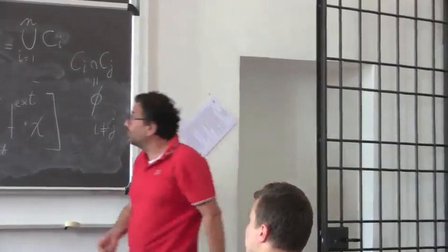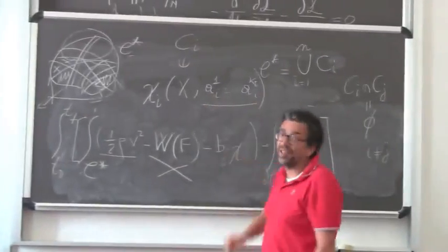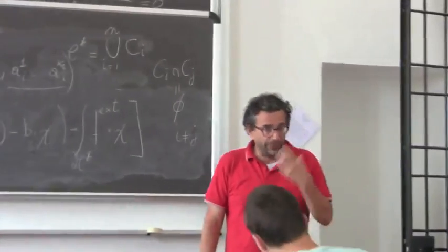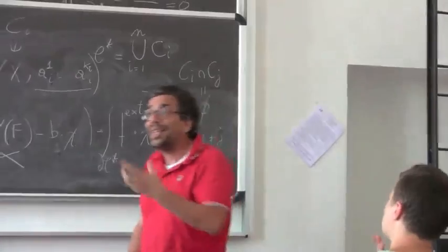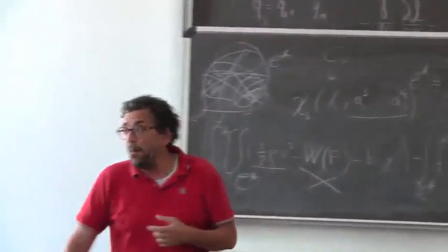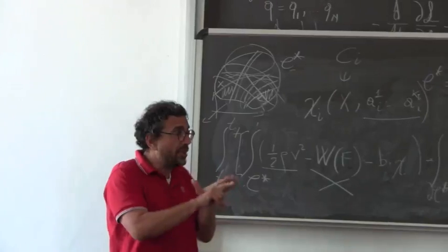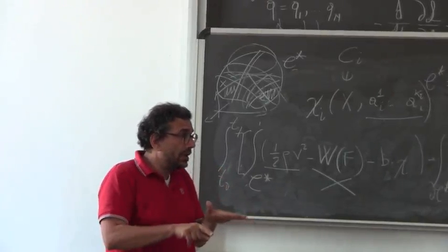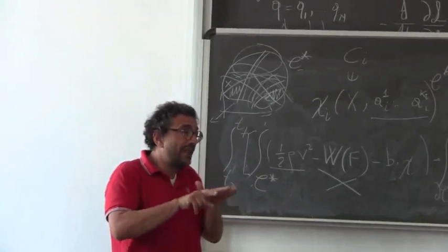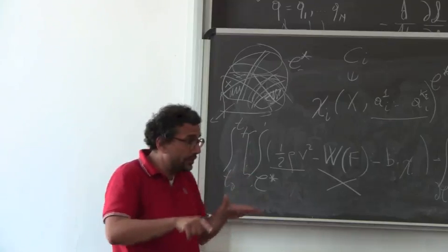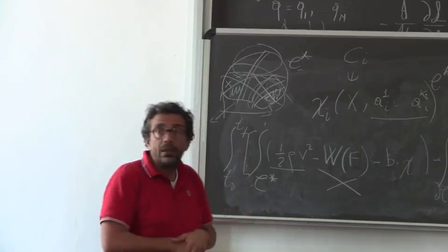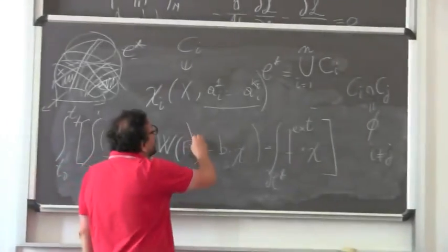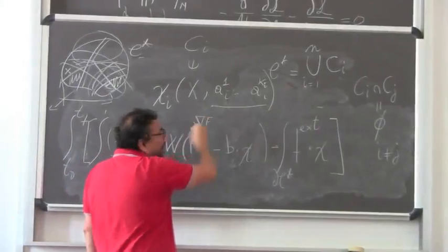So these parameters are not all free. This makes the theory of finite elements different. These parameters must be chosen in such a way that the displacement is continuous, and that the first derivative of the displacement is continuous. Now you understand why people have trouble studying second gradient materials.